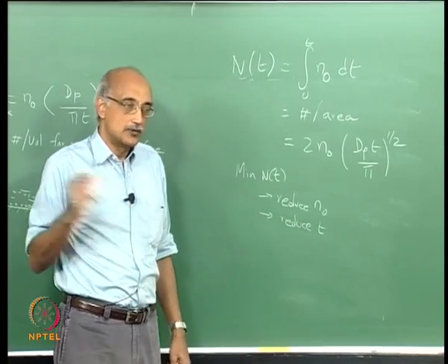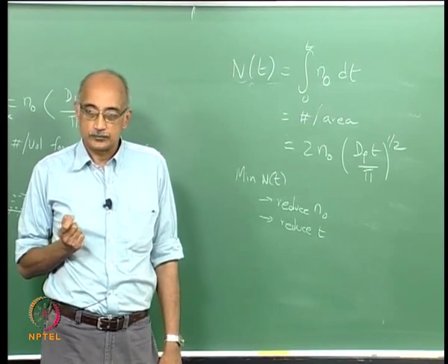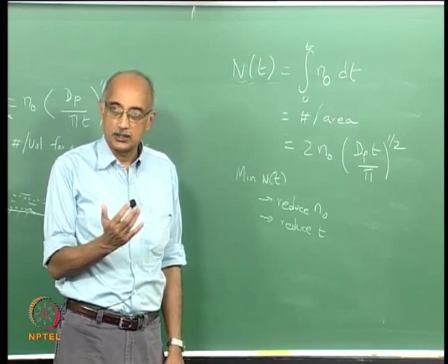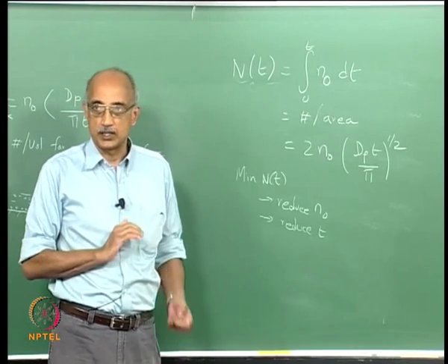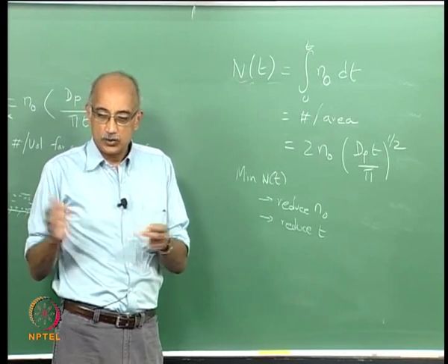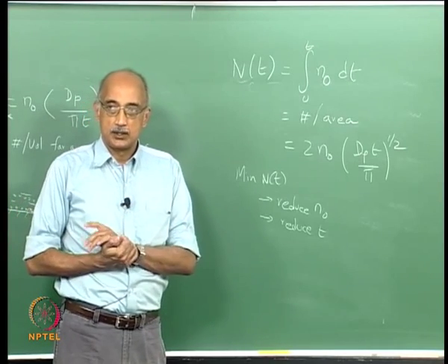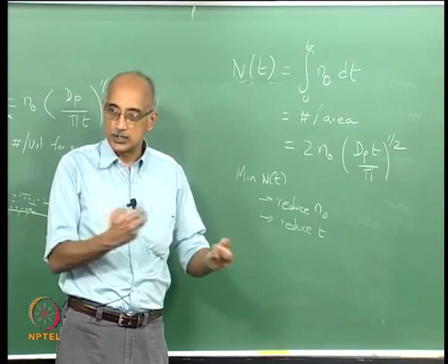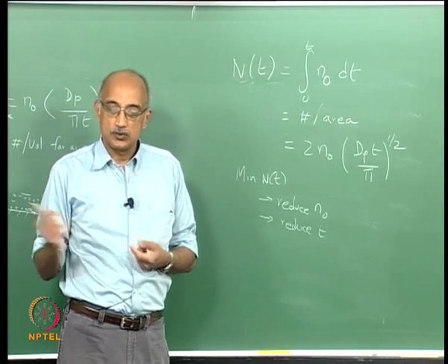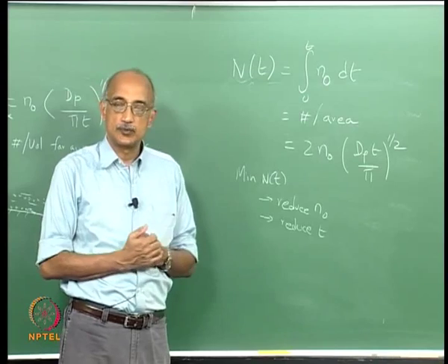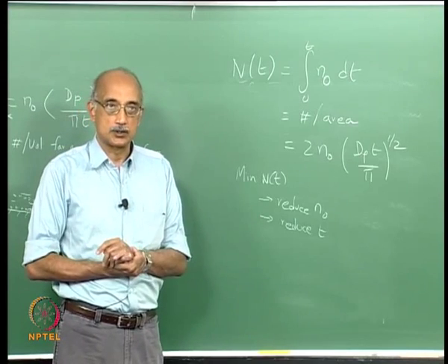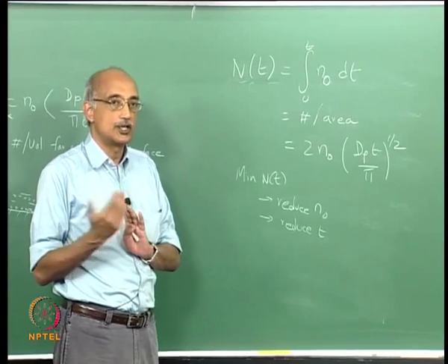Another way to think about this is, if I am running a manufacturing process which is contamination sensitive, I don't want to build up WIP. Have you heard of WIP? WIP stands for work in progress. In manufacturing there is something called CFM, continuous flow manufacturing, where you essentially use a pull strategy as it's known. So basically you don't build up inventory at every stage of your process. The end of the line tells you I am now ready to make a product, so it pulls components. So once you receive that signal, then you start sending material through your process, and you do it in a fashion where it's a continuous flow, which means there is minimum time of waiting for components to be assembled in the next stage of the process. And what you are minimizing then is what's called work in progress, or WIP.